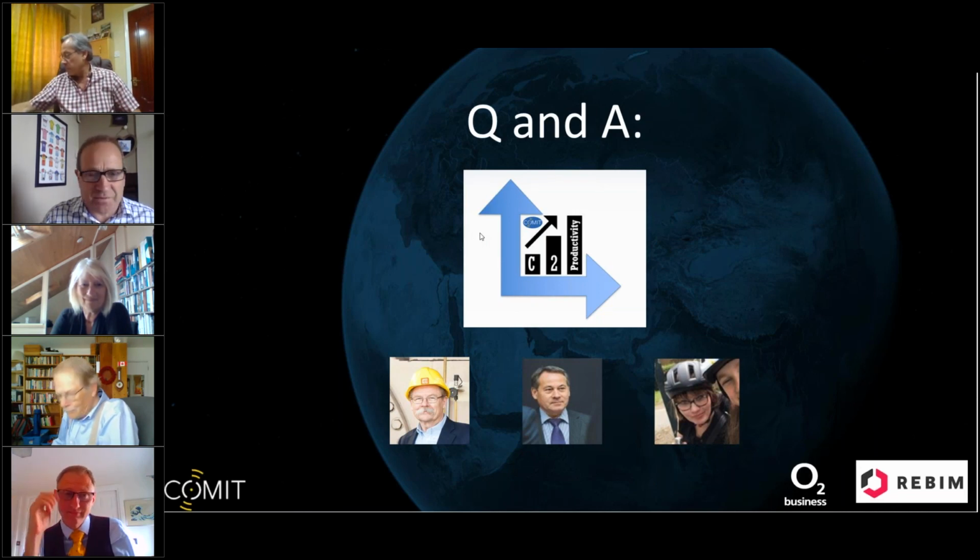I don't know whether it was put in in the 1850s or whenever, but it was considered dead, and it said it had been abandoned on the drawing. But as responsible contractors, we don't take that at face value. So we did some investigations and found there was no gas inside. So we carefully started to remove it. And inside, we found a 150 diameter polyethylene yellow gas pipe.